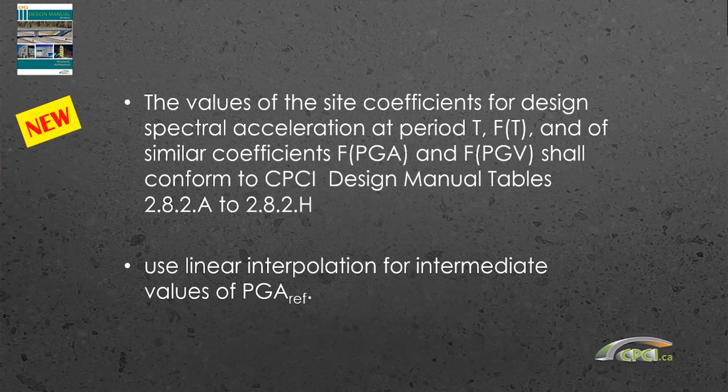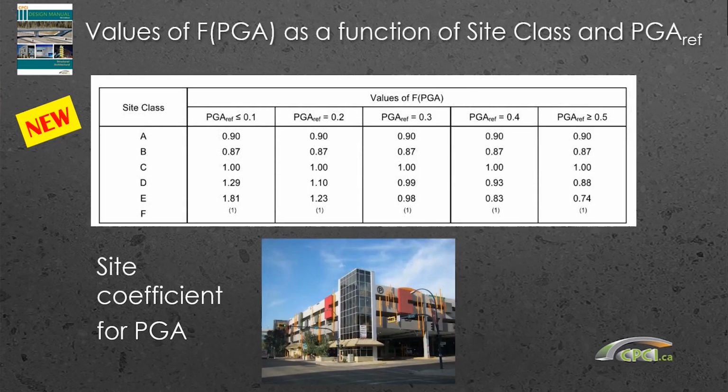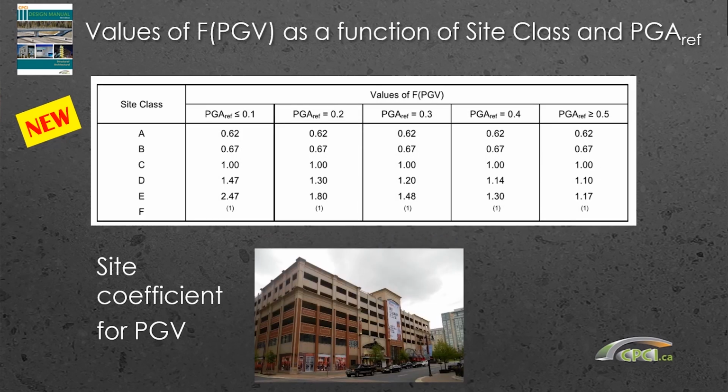So now you really have to look through all these equations for the type of soil, and those are all provided in your manual from the NBC with permission from National Research Council to be reprinted, and obviously you still use linear interpolation between those values. And then new tables for F peak ground acceleration varying with the soil.